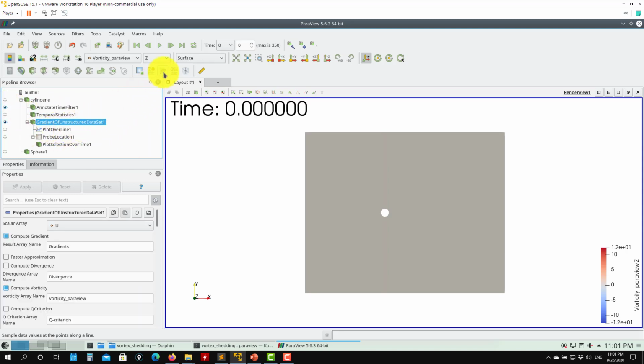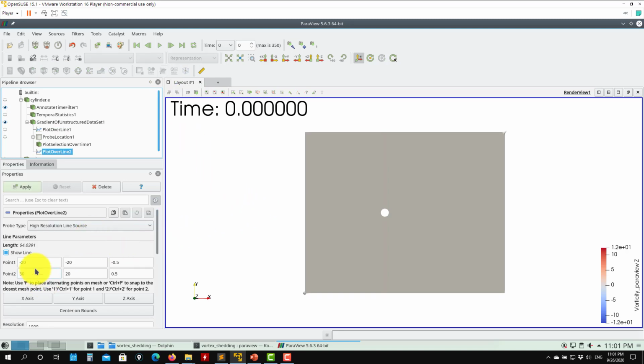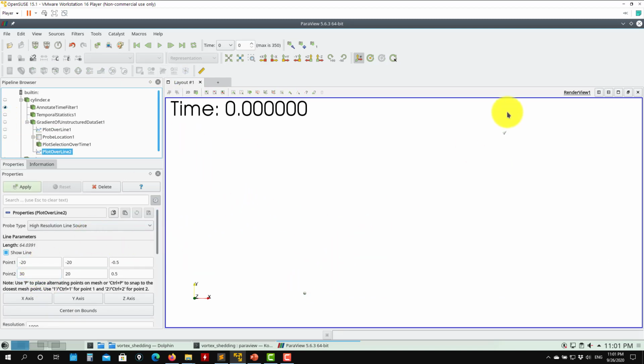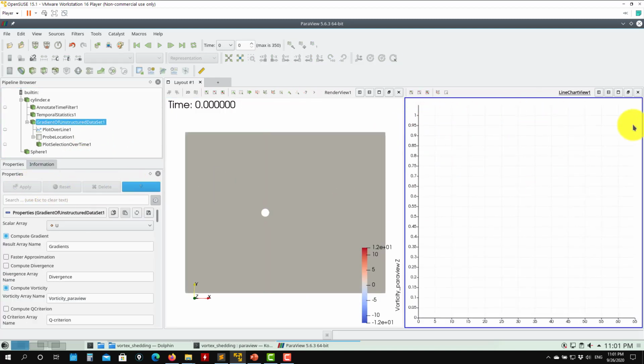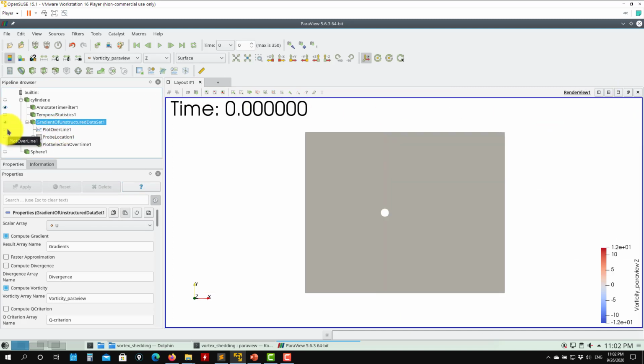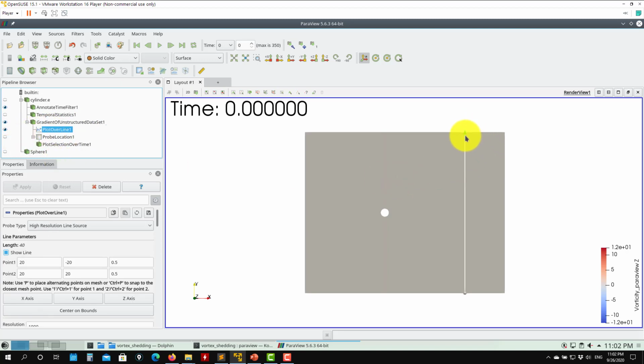So you have it here. As you do this one, you just need to give coordinates. You see here the line, probably this is the line. So give coordinates and then you plot in that line. You know your domain, you know how to do it. In this case, let me go here and see that this is the line that I'm putting in this cut plane, in this part of the domain, in this case the boundary patch. So now what we're doing is just plotting the solution in this line, and you will have that information available for post-processing.